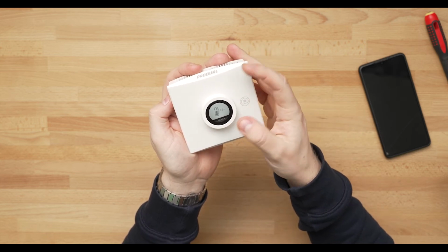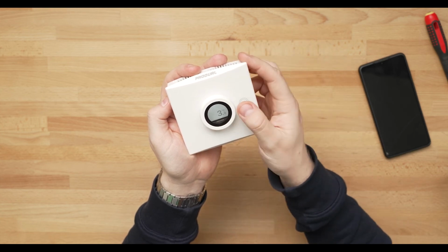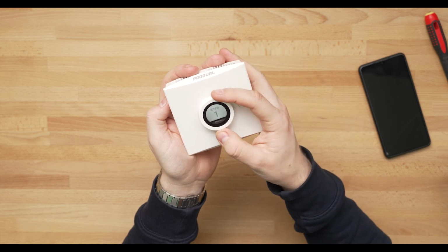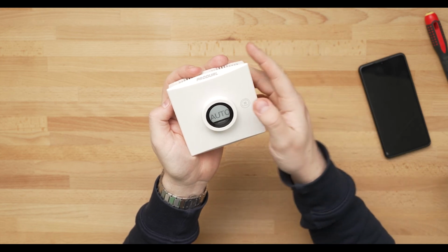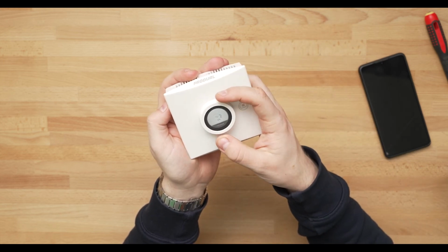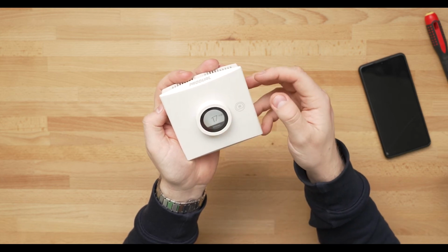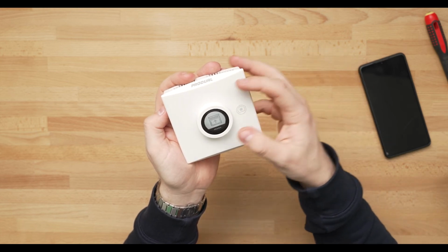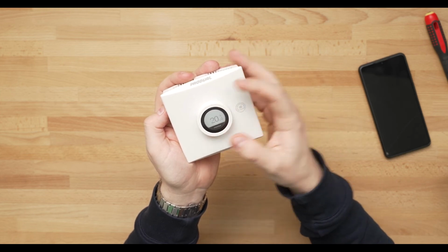By pushing the button we can get this temperature deflection, and same thing here we can do the deflection set point. Next we have a fan speed, and we have here auto, 1, 2, day, night and so on. From here in the extra time we can add extra time with 1 minute steps up to 90 minutes. Here we have a blind control, and by turning we have 10% steps for the blinds.